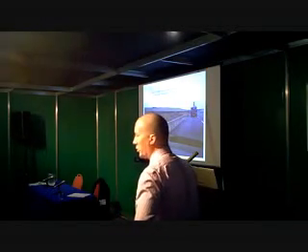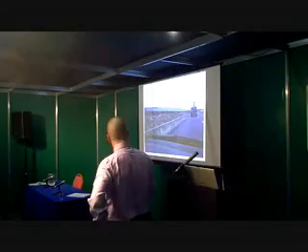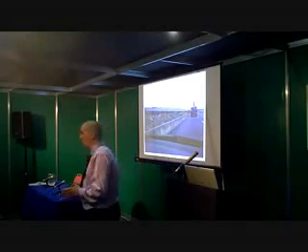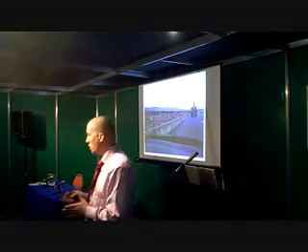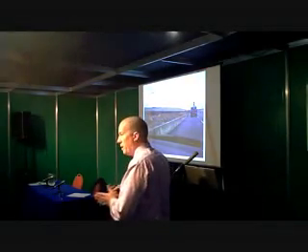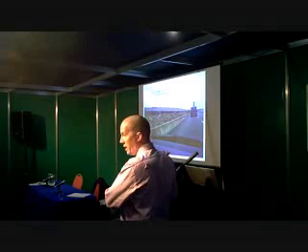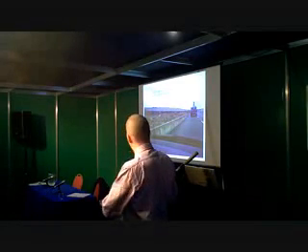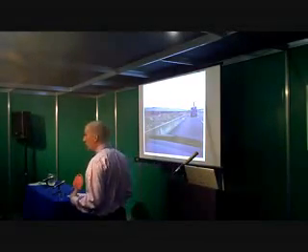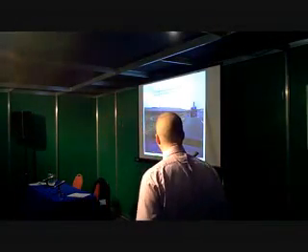Now, you might look at it from the workforce's point of view and say, well, where the vehicles hit the barrier, there's no way now they're ever going to reach the workforce. But the barriers are there and the safety zones are there as a two-way thing. They are also there for the road user. Okay? And in that state, if that's crashed into, the barrier has no containment value for the road user. So he's likely to bounce off, maybe causing further accidents on the carriageway next to where he's had his incident, rather than the barrier acting as it's intended and giving the containment level for the road user and hopefully saving him from possible fatality there.